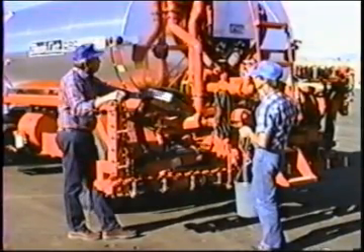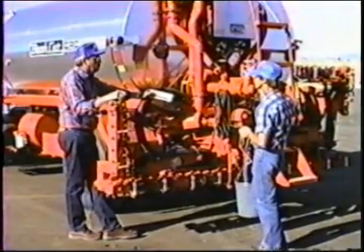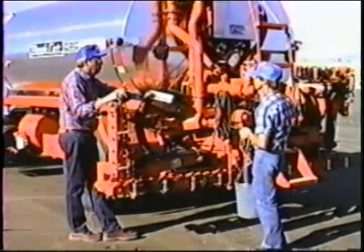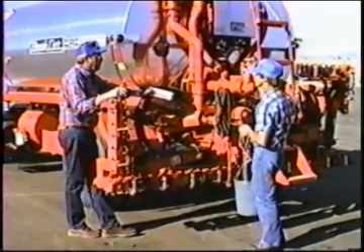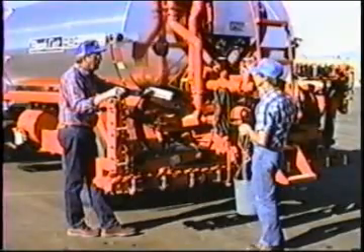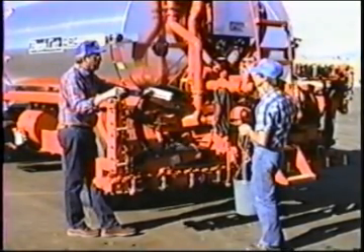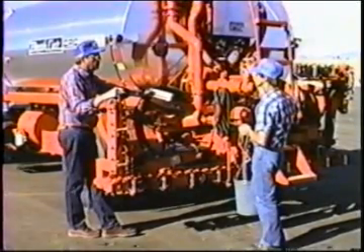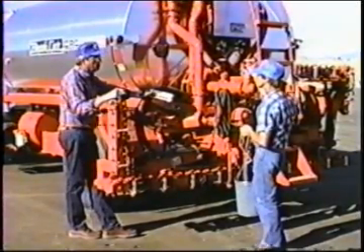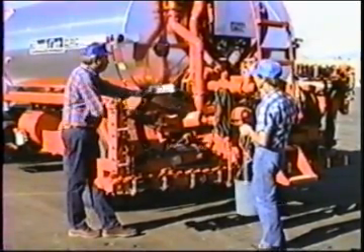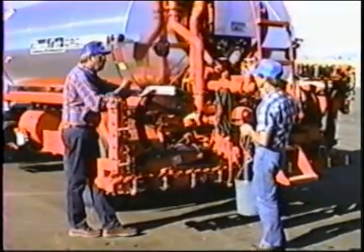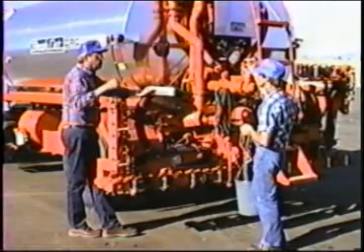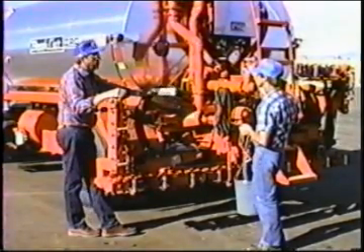Okay, again, remember, if we were spreading manually this way, not with the computer, but manually, and we've made that setup, as long as we stay in that gear that we set up in and we stay at that bar width, our spread rate is going to be exactly right. We can speed up or slow down, and because it's driven by the hydrostatic transmission, which is in the end tied to the ground because of the wheels and the driveline and the transmission and whatever, everything is relative.